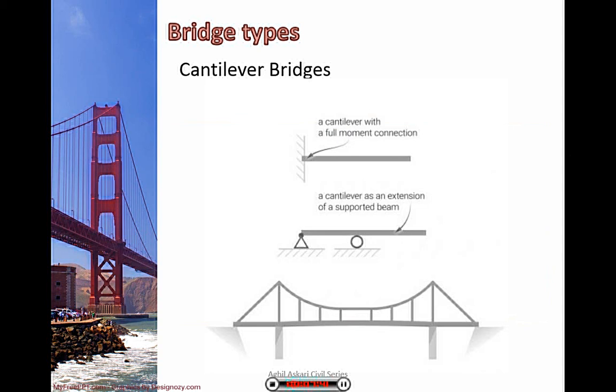However, the two cantilever arms are connected by what is known as the suspended span, which is effectively a centerpiece which has no direct support underneath. The bridge load is supported through diagonal bracing with horizontal beams as opposed to typical vertical bracing.